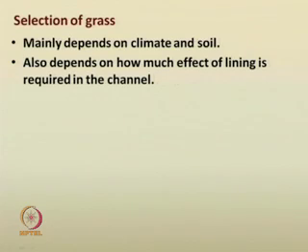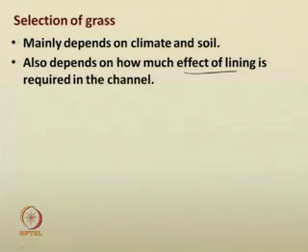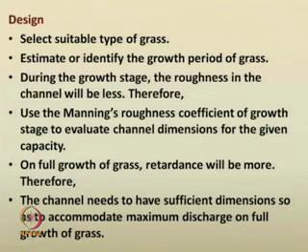You also need to consider how much effect of lining should be there. Maybe you are constructing a channel in such a way that you are allowing partial erosion, but the grass cover is made only for temporary prevention of erosion. Otherwise, you are permitting some sort of erosion, but not in a higher magnitude. Based on that aspect, you can use appropriate grass covers. So, how much effect of the lining is required, based on that you can select your grass.